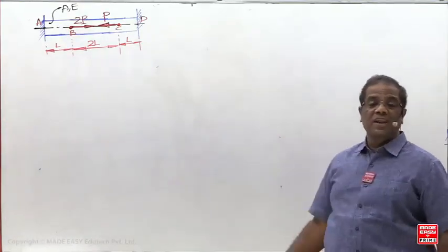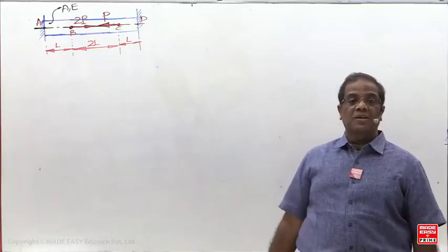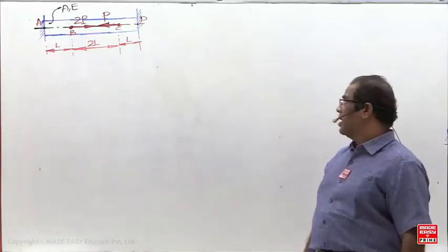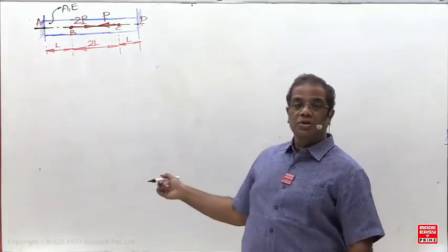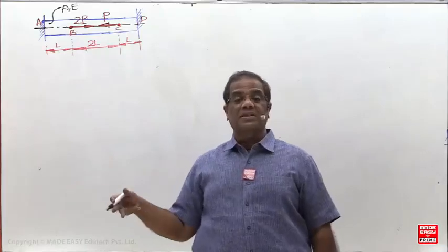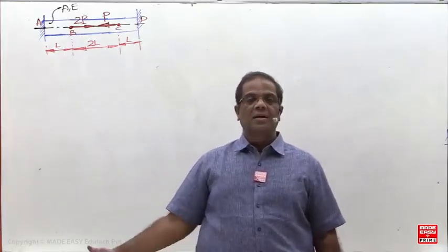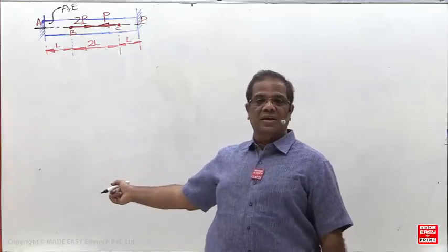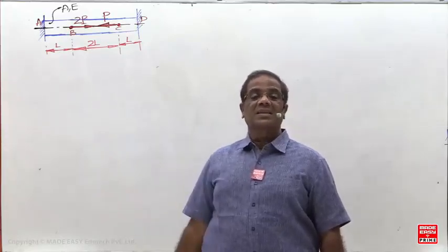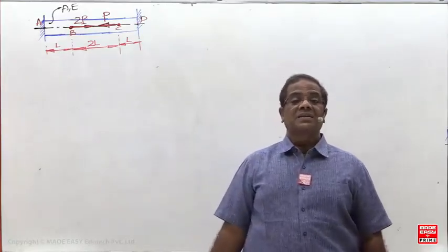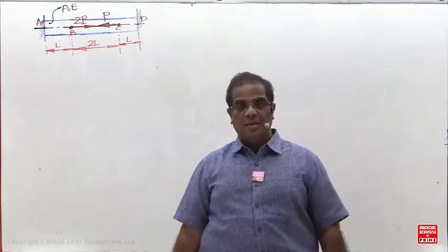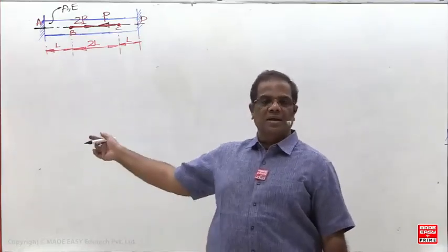Now below this one, leave some space. At the end, we'll draw the ALD. This question can be done by two methods. Always the first method is the actual method, about whatever you have studied. Reactions are determined with the help of the static equilibrium equation and compatibility. That's the first method. Same thing.